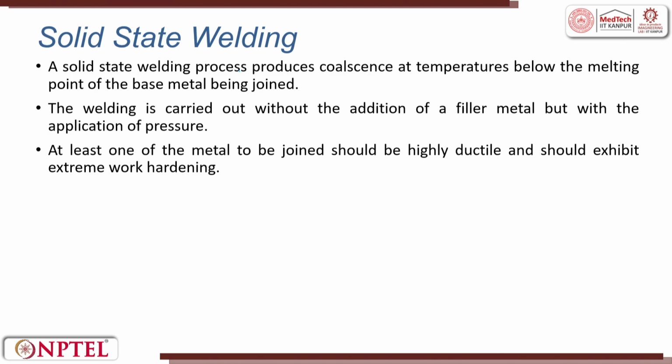The welding process produces coalescence at a temperature below the melting point of the base material being joined. So, you have material A, you have material B, it can be similar, it can be dissimilar, joining between these two, where the temperature of the weld is less than the melting point of the parent material. The weld is carried out without the addition of a filler, but with the application of pressure.